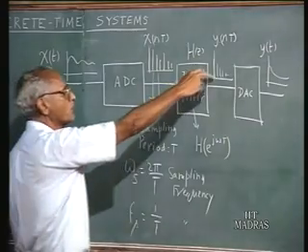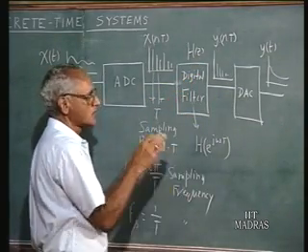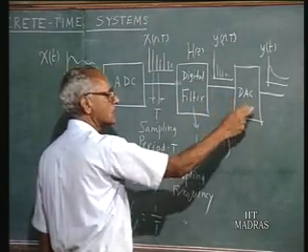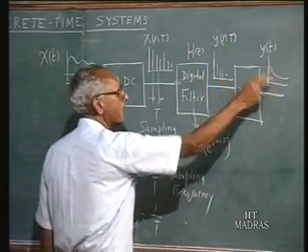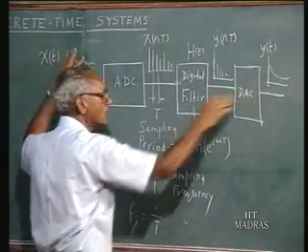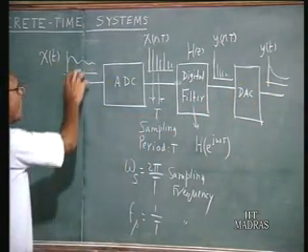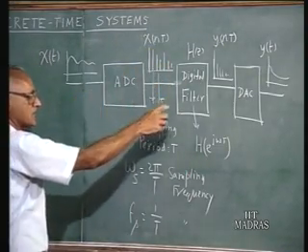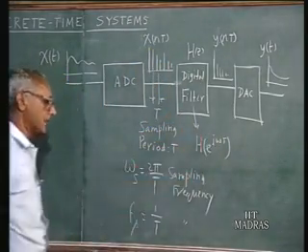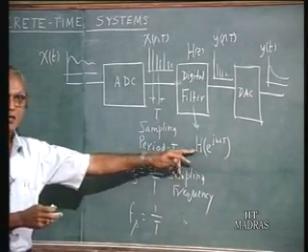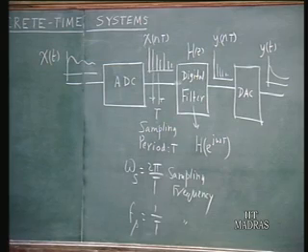And once you have the output sequence, you put it through some filters to remove the high frequency components and so on. This is what is called the analog reconstructor. You can recover back your y(t). So, given an analog input signal, you get an analog output signal, but in between you convert this into a discrete time signal, and the frequency response of the system is characterized by H(e^{jωT}). So, you design your filters so that this H(e^{jωT}) has the desired variation with reference to the frequency.